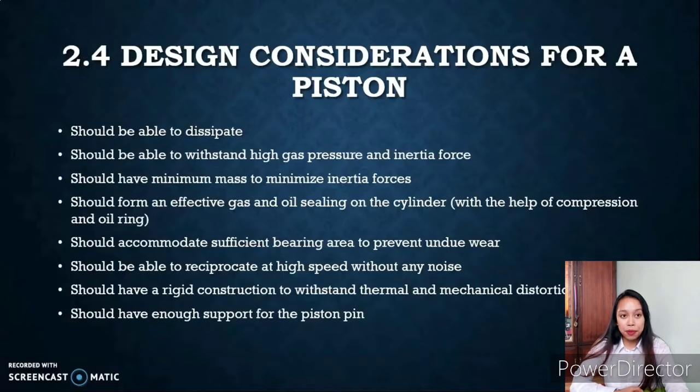Secondly, it should be able to withstand high gas pressure and inertia force. Thirdly, it should have minimum mass to minimize inertia forces. Fourthly, it should form an effective gas and oil sealing on the cylinder with the help of compression and oil ring. Fifth, it should accommodate sufficient bearing area to prevent undue wear.